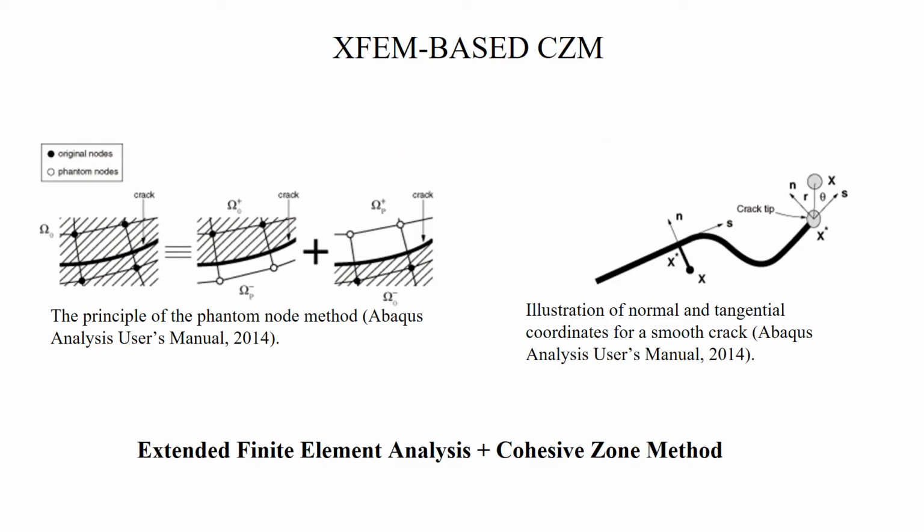So we chose to use XFEM-based CZM for our model, which is a blend of the extended finite element method and the cohesive zone method. XFEM allows an arbitrary, solution-dependent propagation path in which the mesh is independent of the fracture. This makes the simulation much easier as remeshing is not required. XFEM incorporates enriched functions in the crack domain to account for the displacement across crack surfaces and the singularity at the crack tip. The cohesive zone method allows the use of phantom nodes to incorporate traction-separation cohesive behavior and allows the crack to move between element boundaries.